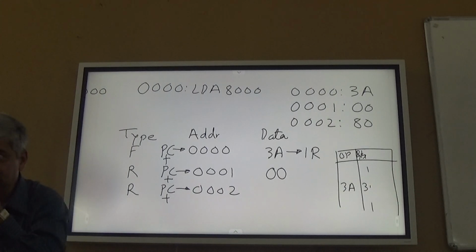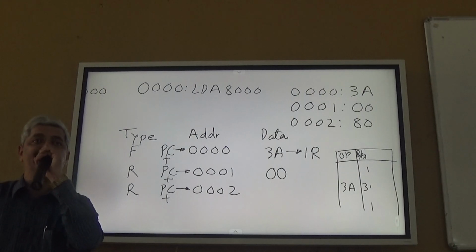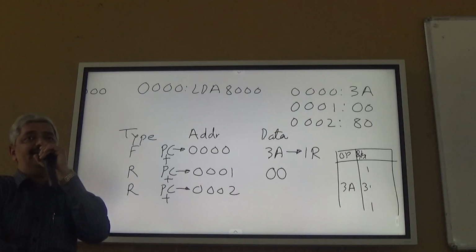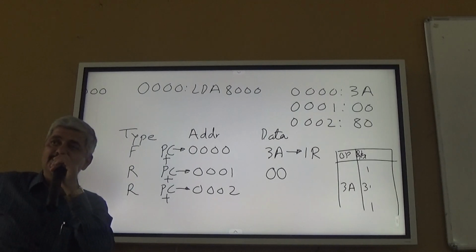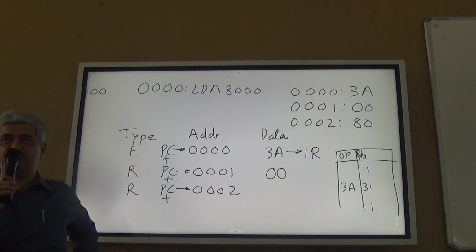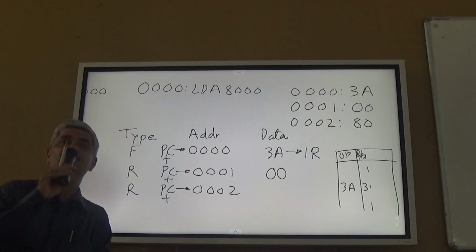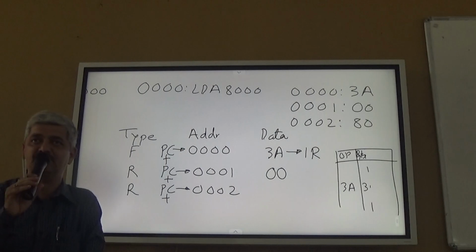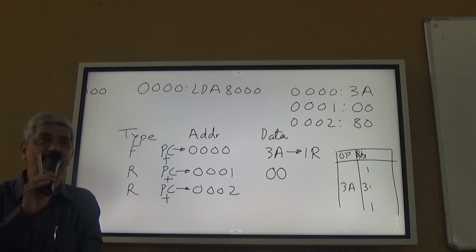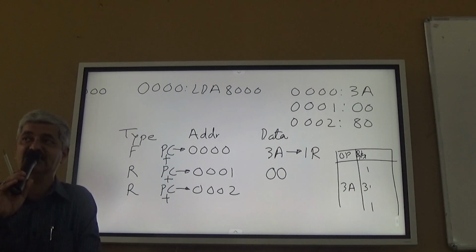Therefore, 2 specific temporary registers W and Z, W being higher byte, Z being lower byte, have been provided. So the WZ register pair is provided as temporary registers which are not used by the programmer for programming. So there are no instructions which can access these registers, meaning no MVI W, MVI Z, or MOV A, Z instructions.